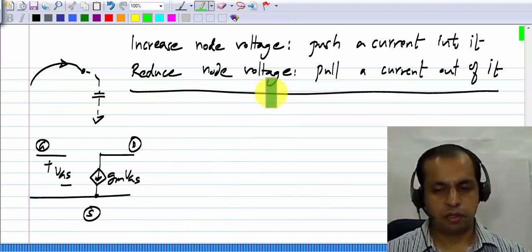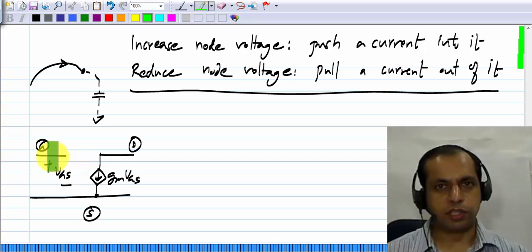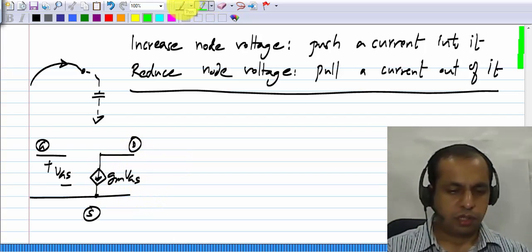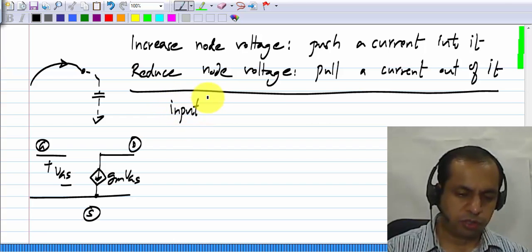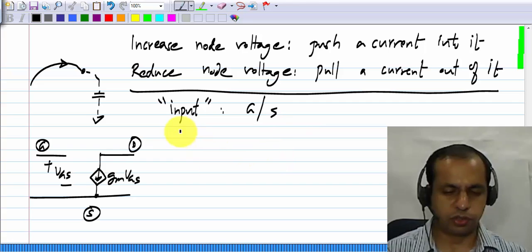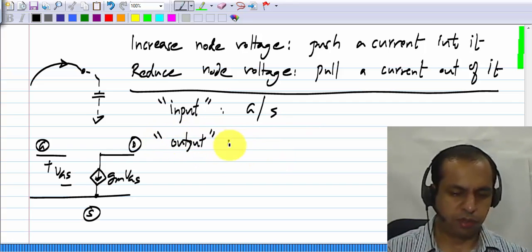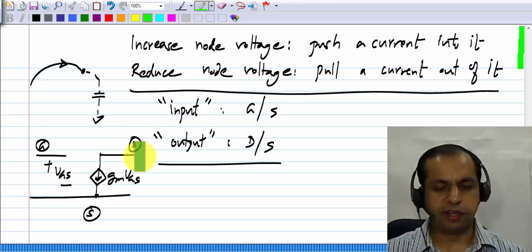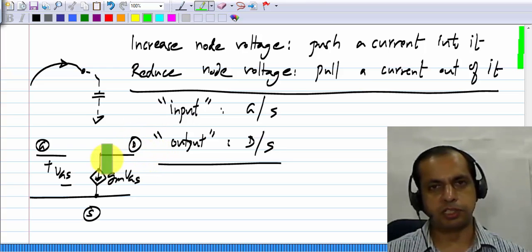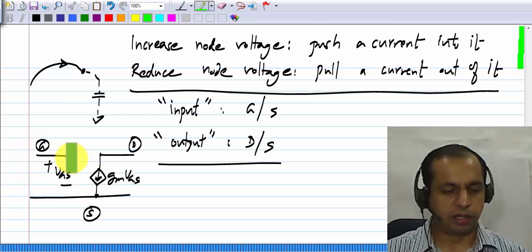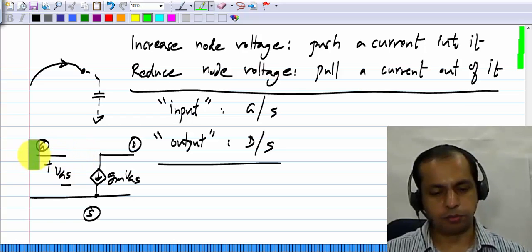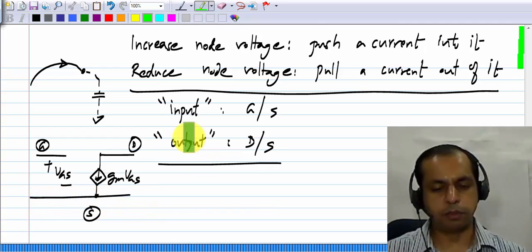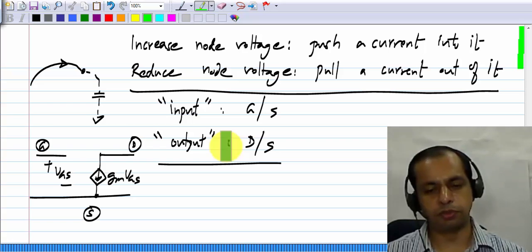Also, you can see that in a MOS transistor, the cause is applied between gate and source, and the effect appears from drain to source. Okay, so the input can go to either gate or source, and the output can come from either drain or source. Okay, we'll see examples of both. And of course, drain can only be an output. You can't apply something to the drain and expect something to happen. And gate is only an input. You can't expect anything out of the gate. Okay, no signal comes out of it. The source can be either. Okay, so the source is part of both the controlling side and the control side, and it can be either input or output. And again, we'll see examples of both of them.